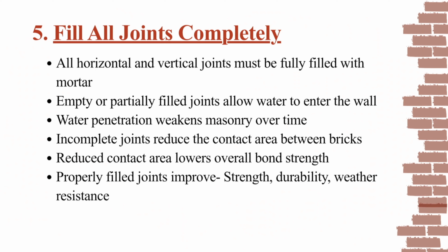Now rule number 5. Fill all the joints completely. All joints, horizontal and vertical, must be fully filled with mortar. Empty or partially filled joints allow water to seep in, which weakens the wall over time.